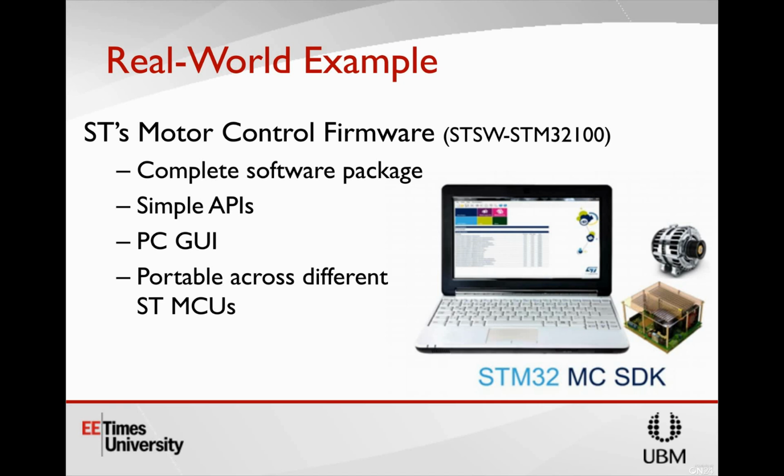Good question. The system performance will be better with an encoder. If you're doing a speed control system, it'll regulate the speed much, much more tightly with an encoder, because you have much finer resolution. There are no filtering delays, no processing delays, or a lot of noise entering your calculations, so you can get very accurate speed control. With sensorless, you often have filters and a lot of mathematical processing on those phase currents as they come back in, and so it can cause delays, and the system can be a bit more sluggish than it would be with an encoder.